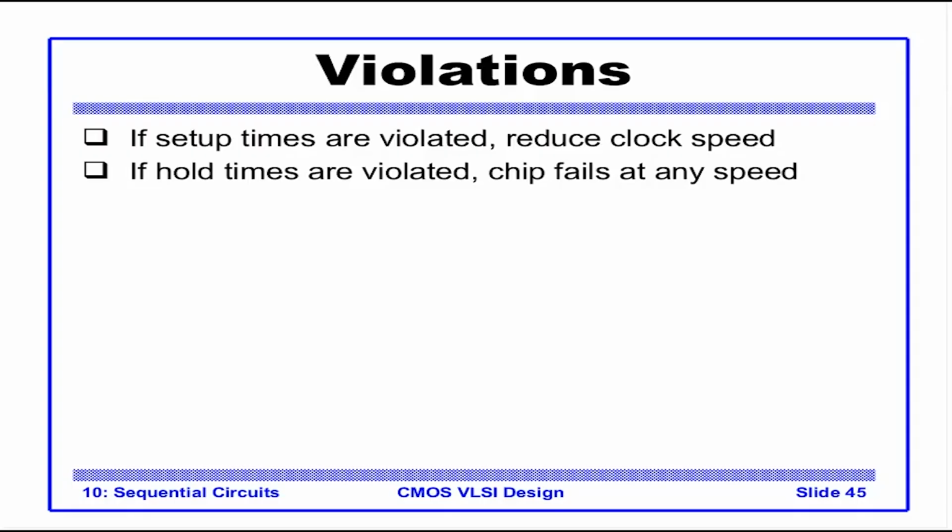This is the reason why designers are more alert, more wary of the hold time cases when compared to setup time cases. So you have to make sure that hold meets in all the cases. What do all cases mean? It means all the voltages in the voltage range for which the chip is specified. It means at all the corners of the temperature range. It meets in the slow process as well as the fast process. We will see the cases later.